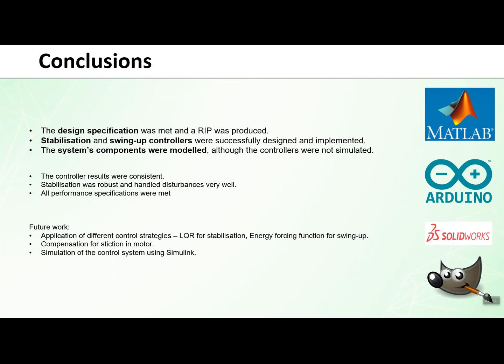It was difficult to compare this rotary inverted pendulum to those in research due to the use of two PID controllers. It was determined, however, that this system could outperform many other controllers when subjected to disturbances. This robustness is a known benefit of PID controllers. It is also to be noted that the swing-up routine used in this project was not feedback-based, so the swing-up was much faster than most in literature, although not robust.